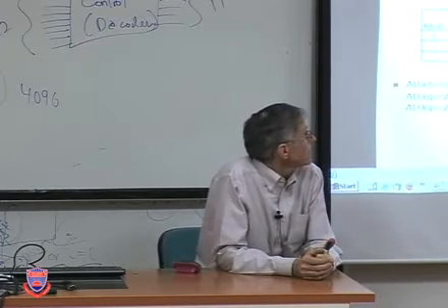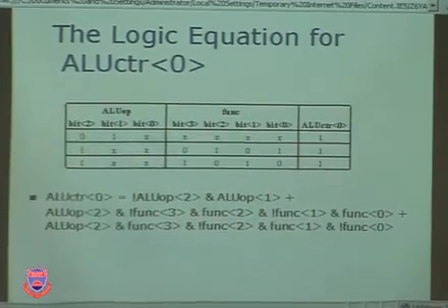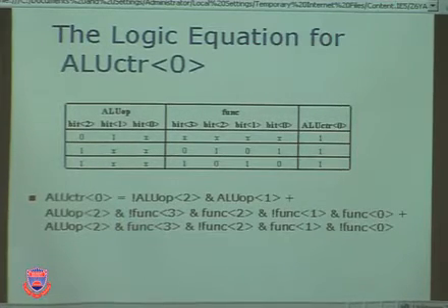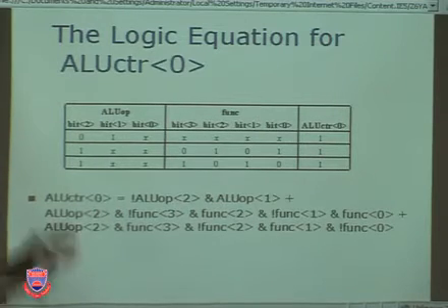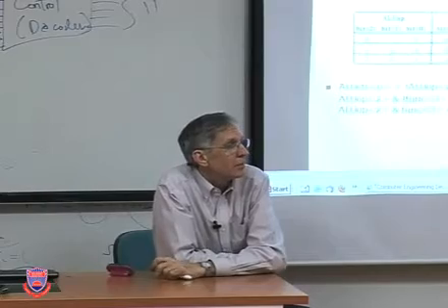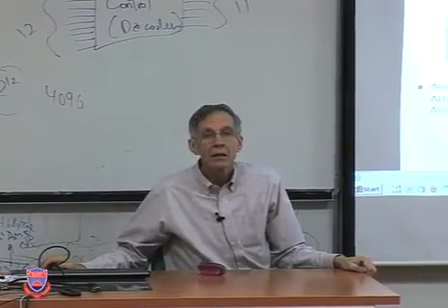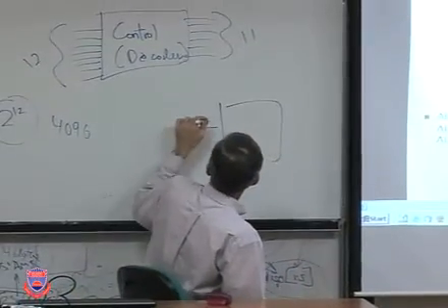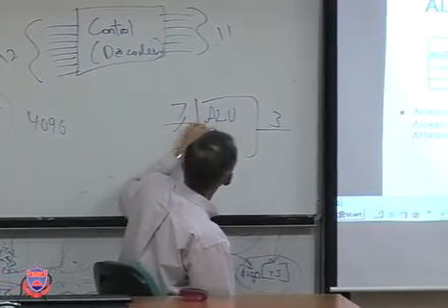Now, I'm going to just suggest to you, since there's 1, 2, 3, 4, 5, 6, 7 inputs to this, you would probably be struggling quite a lot to get a perfect minimization through Karnaugh maps, because that would be a 7-variable Karnaugh map. Not nice. Well, your choice is, okay, go get yourself a computer program and run the minimization and enter all this data. But you know what? This is pretty clever and pretty quick. A pretty fast way to get the job done. Minimize the bits. So what have we done here? What have we got? We've got the input-output relation for the 7 input, 3 output ALU decoder.